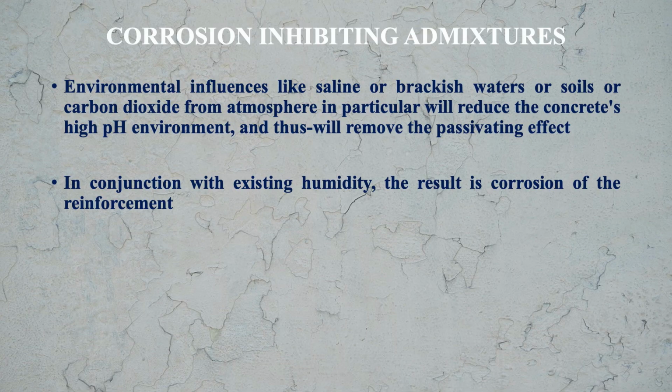In conjunction with existing humidity, the result is the corrosion of the reinforcement. Means when salinity is introduced, this salinity mixed with the humidity reduces the pH of the concrete, and hence in such an environment corrosion of the reinforcement will take place.